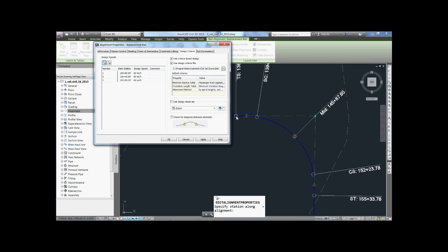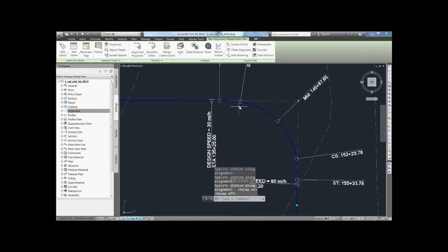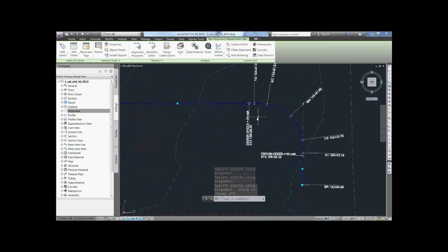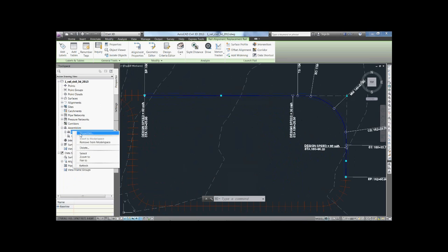Now, it's worth noting that while Civil 3D includes design standards for rail, it can be customized for any sort of specific object. The whole purpose of these design criteria is to avoid manually checking each element against the standard using the traditional methods of lookup tables and manual calculations. Using this method will save you time and allows you to take advantage of design criteria, so you can spend that time adjusting your design instead of looking up each element table by table.